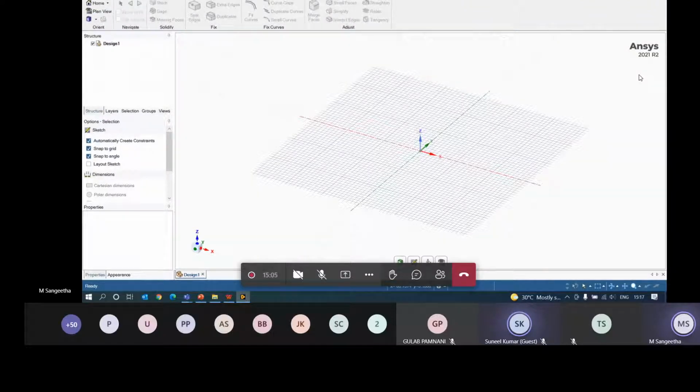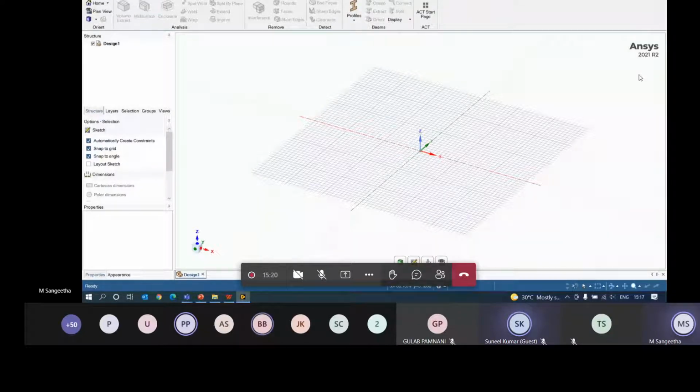The most important thing that we consider in terms of working on a simulation is where you design geometry on different platforms. That could be any CAD tool, it can be SolidWorks, Creo, CATIA, anything. But when you are trying to import it for simulation, there is a GUI change with which you get to see a lot of differences in your geometry, and it will not give you a proper geometry.